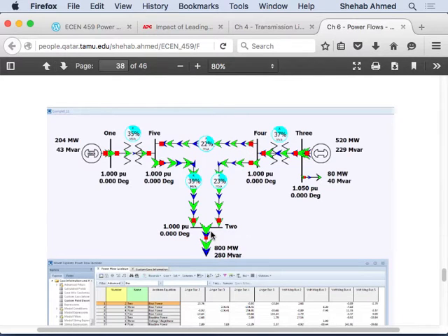We would expect that even though I'm controlling the voltage to be 1 per unit around the system, the angle between bus 2 and everybody else's angle would be significant, right? And we're measuring everything with respect to the slack, so we're taking the absolute angle at this bus, delta at bus 2. This is what we're solving for in the power flow equation.